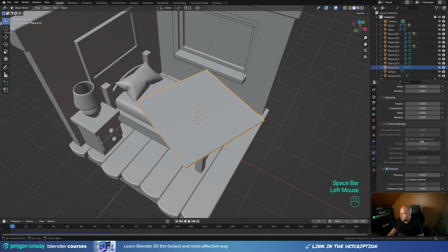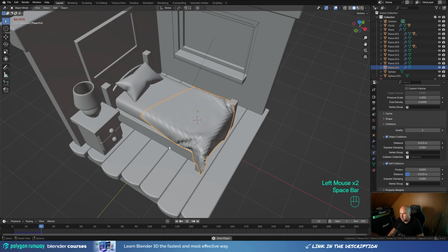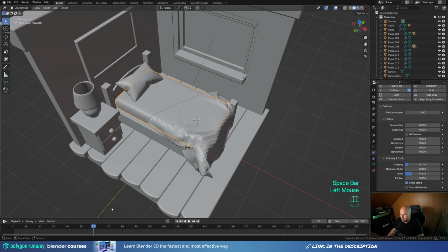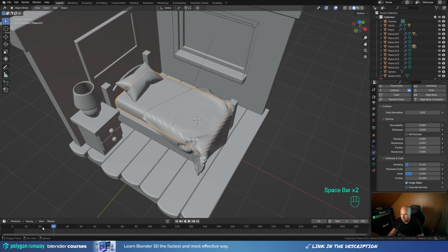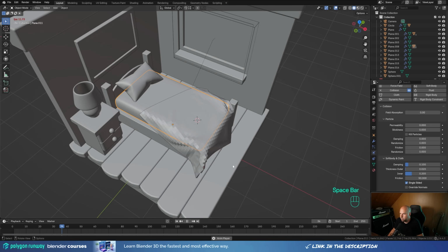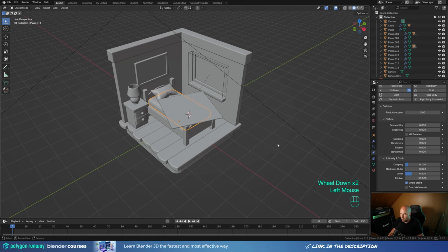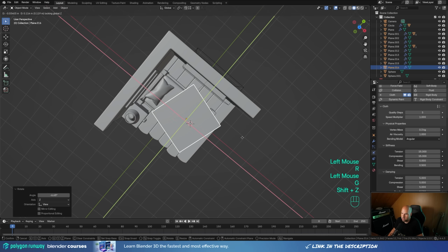Okay, and the other thing we can do is some self collision. So in the collisions, enable self collision so it doesn't go through, and we'll need some damping. So let's select the collider here, and in the soft body and cloth, let's increase the friction to something like 20. It still slides, so let's do something like 50 here, and now it barely slides, so I think this will be okay. And this looks just fine, so maybe I'll just reposition it a little bit on the x-axis here, change the rotation.